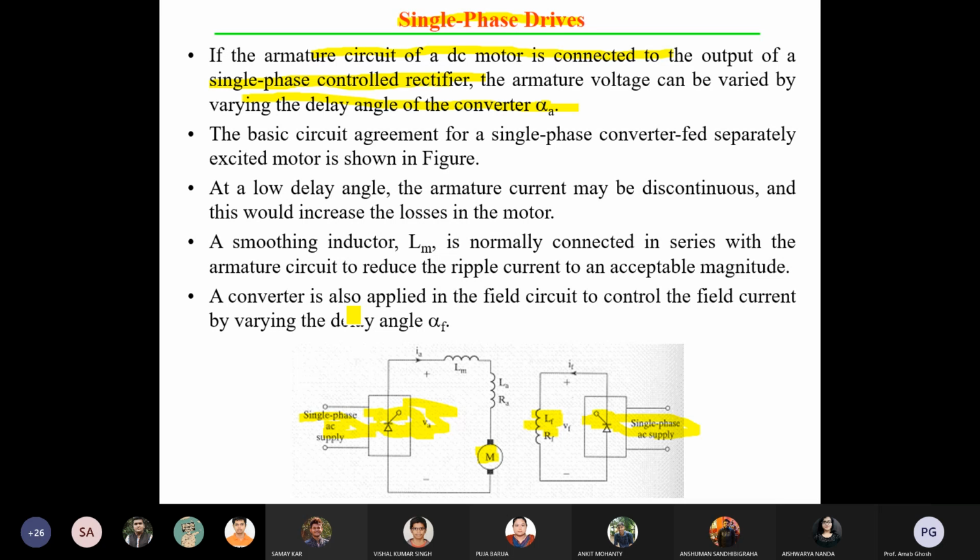It would be unnecessary. Suppose your latching device is turned on. If you are using a pulse train for a longer duration, all that time it is trying to turn it on, so unnecessary power loss will be there. That is why you have to give a high frequency mixed DC signal with very small durations. After getting the small duration, the device can be turned on. That is the idea.